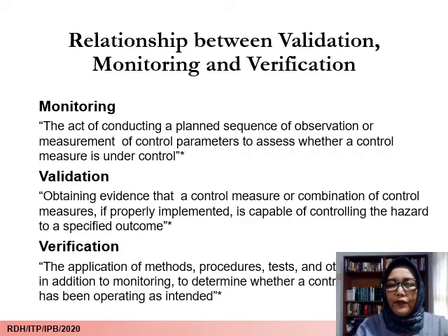So for example, if we are going to pasteurize milk, during the pasteurization, we are going to have somebody monitor whether, for example, a temperature of 80 degrees for 15 minutes is achieved.